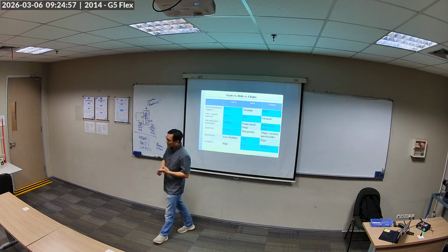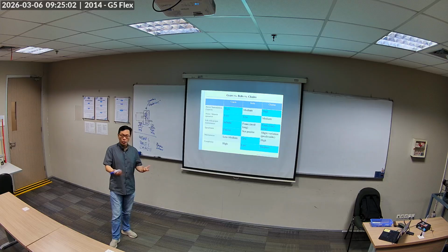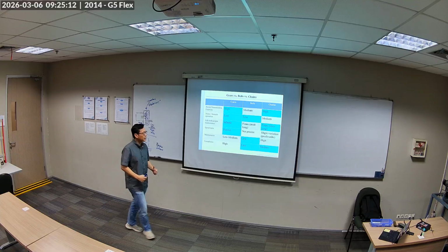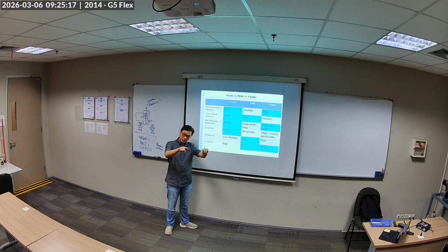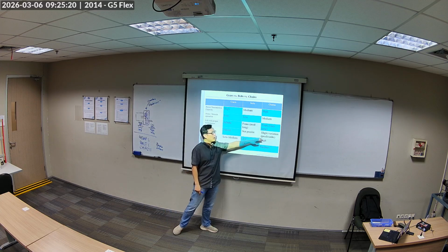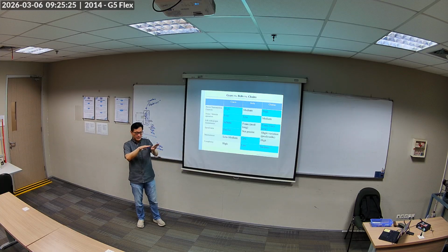Chain is predictable, but there is some fluctuation, believe it or not. So when you don't feel it, because like in your bicycle, the ratio actually fluctuates, but you don't feel it because the tires are flexible enough to absorb any fluctuation. And besides, your legs are not that sensitive anyway. But there is actually a fluctuation in the speed ratio for chain. We'll talk about that. It's because of the chordal rise. It's because the chain link kind of climbs onto the sprocket. And every time it does that, the effective radius actually changes.